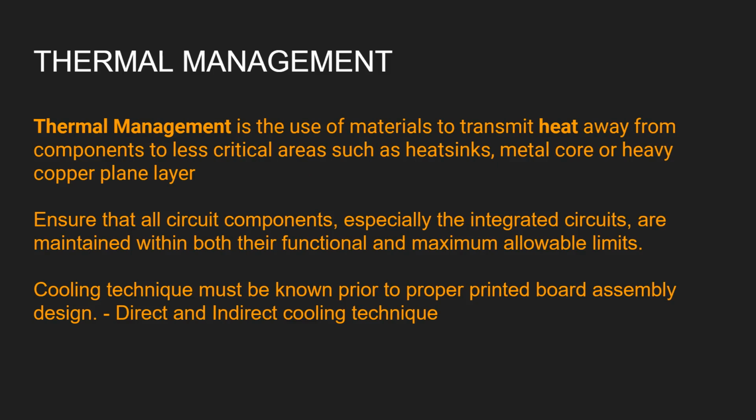So why do you think this thermal management is important? It is important because when you have a circuit board or a device, let us take just the microprocessor for example. When you switch it on and you have all this circuitry working inside, we know that there will be heat generation because of losses, I square R. So if this heat is not removed or dissipated efficiently,